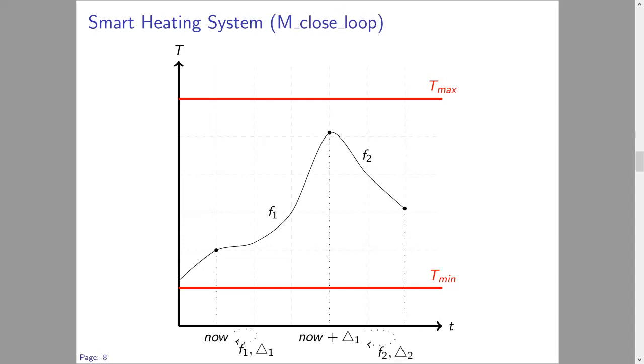Then we refine the inductive construction step, specifying that each piece in the time series to be constructed experiences the full cycle of a simplified closed loop architecture. Please see the bottom of this figure. At each cycle, the discrete control, to be designed as a black box first, needs to predict a safe trajectory over the next cycle. Then the discrete control passes the initiative to the continuous system, where the predicted trajectory is used for system progression. Finally, the continuous system passes the initiative back to the discrete control for the next cycle and closes this loop. The intuition of this refinement is that by the closed loop architecture, we delegate the construction of a safe trajectory at each cycle to the discrete control.